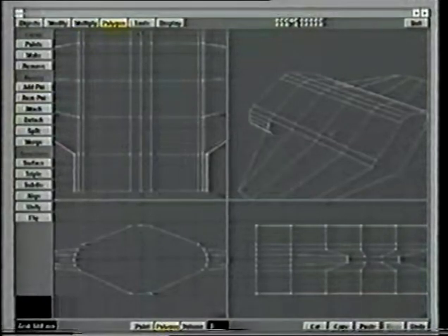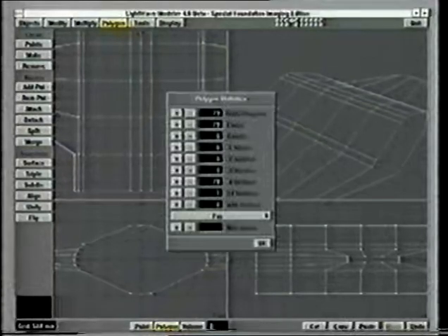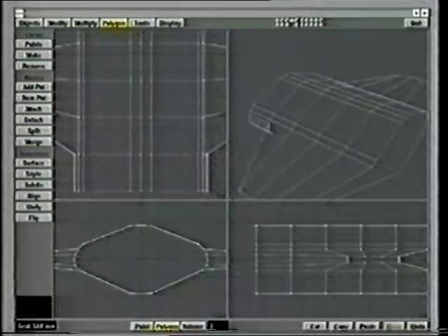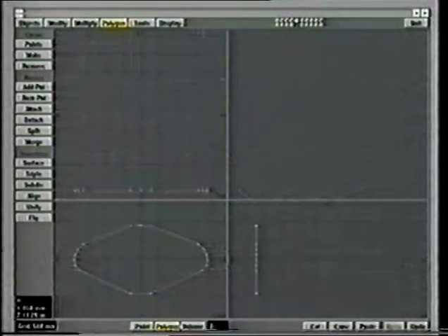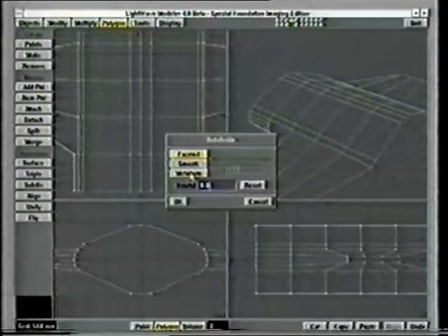So obviously I've still got bigger than quads in there, so let's find out where they are. Hit the W key, we've got 1, and there it is. Let's cut that and paste it into the other layer because I want to keep it for later. Right, so let's go and run our subdivide and use metaform.